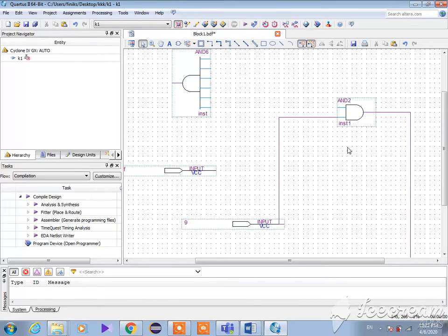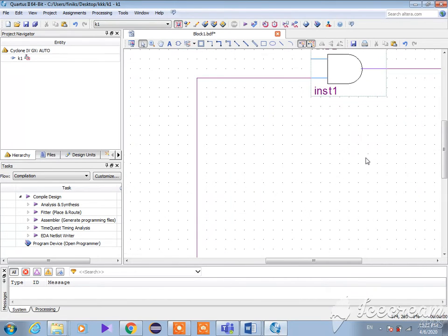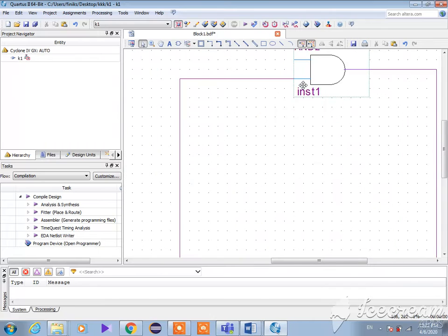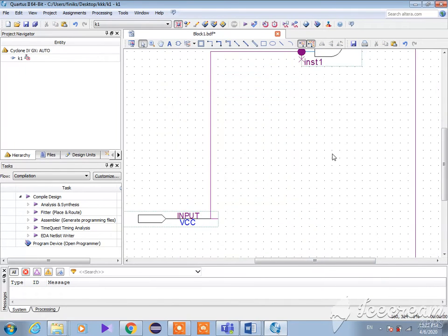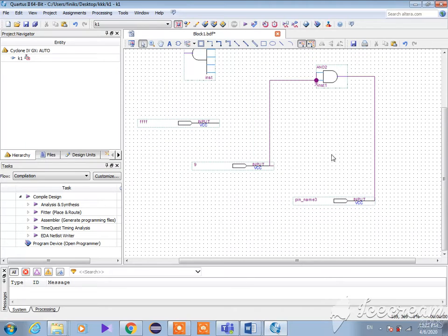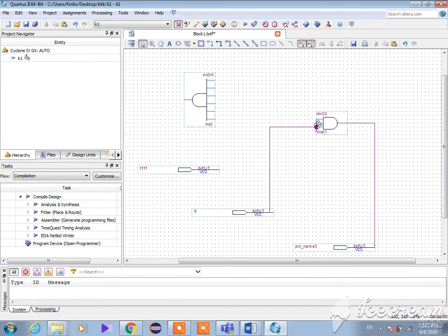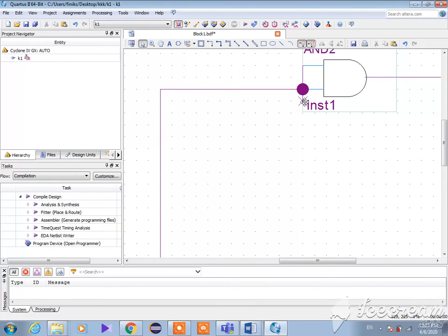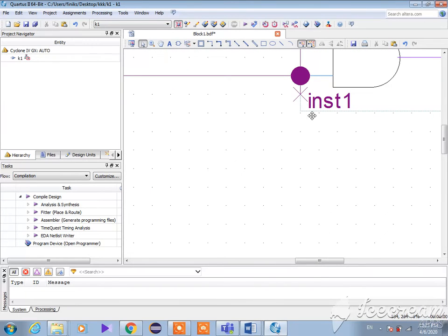Okay, the wiring is so important, so you are going to use zoom in and zoom out and check the input because you have a problem. You can see the problem, but for example, when you are not zooming, maybe your circuit is crowded and you cannot detect it, but when you zoom in, you can find the problem. This is so important, and in compilation you have a problem and it says the wiring is not correct.